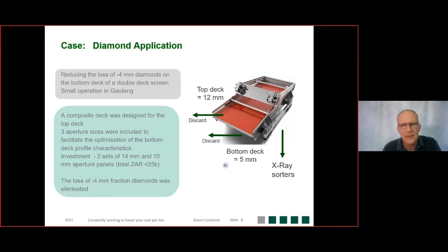And as they start going through, your middle section will have an increased bed depth as the undersize now starts going through that screen deck. And then finally on your third section, you will have most of your near size that hasn't been screened through. They will then typically go through on the discharge end in that third area.